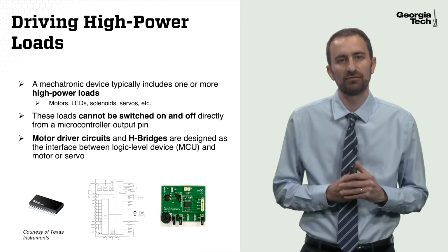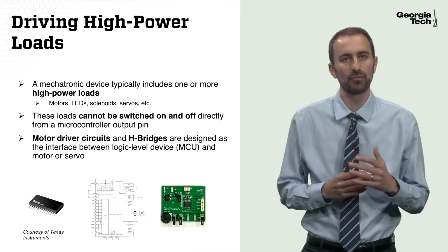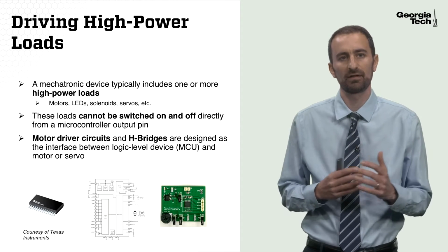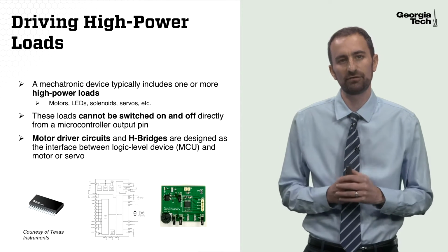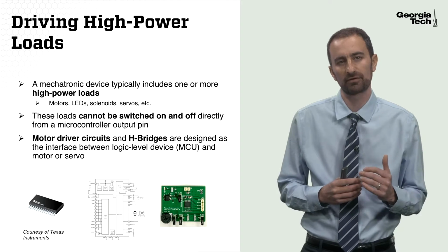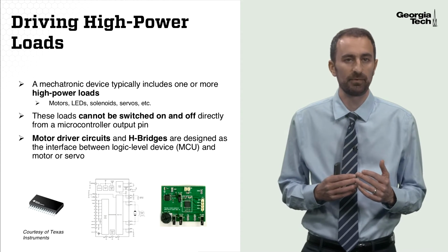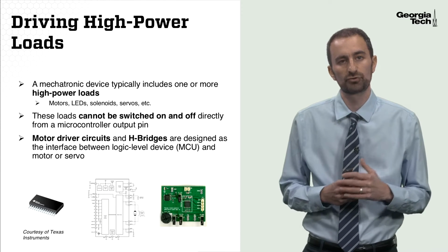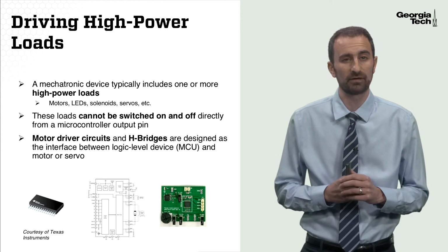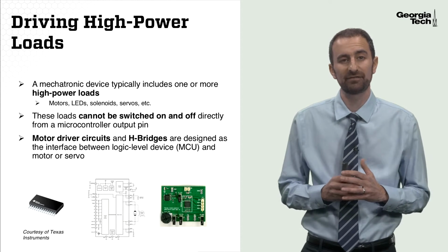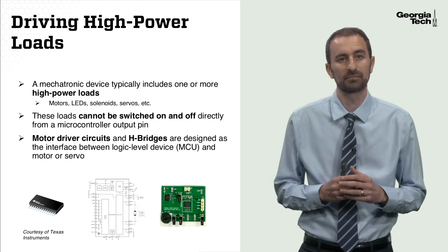A mechatronic device typically has one or more high-power loads, and these loads are things like motors, LEDs, solenoids, servos, etc. Now, we can't switch these loads on and off directly from a microcontroller output pin. We can't drive them from an output pin. These loads will draw too much current for us to source that current directly from the microcontroller. And likewise, we can't sink the current through these loads into the microcontroller output pin.